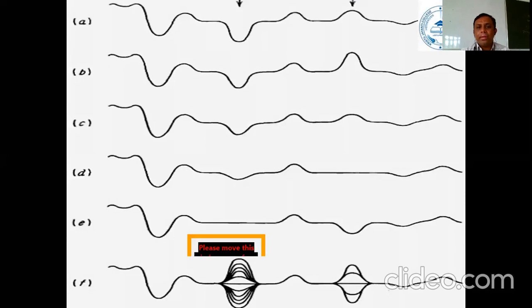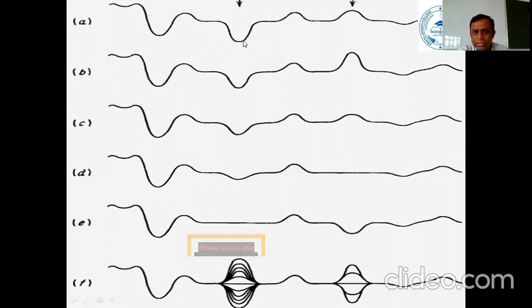So this is how the radar will identify the moving target. Now maybe I can show you a graph. This is the signal I am getting from the first pulse, and this is the signal I got after the second pulse. When I compare these two signals, you can see that there is no change in the phase shift between transmitted and received, so there is no moving target.